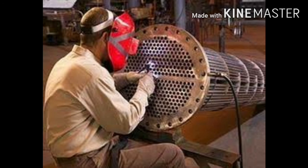Number 6, install new gasket, mainly on the head, carefully to avoid leakage. Improper installation will lead to leakage. Okay, that is very important. Number 7, hydrostatic test. After the maintenance job is secured, be careful to do this job safely because a high pressure will be applied.